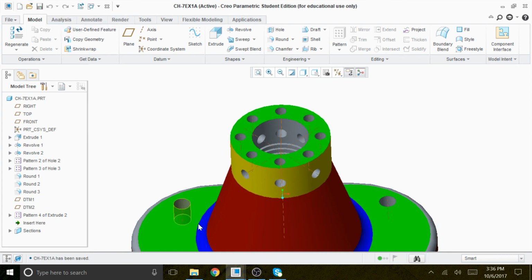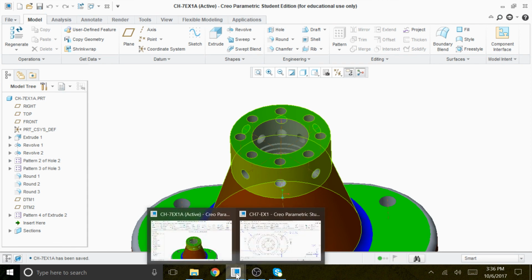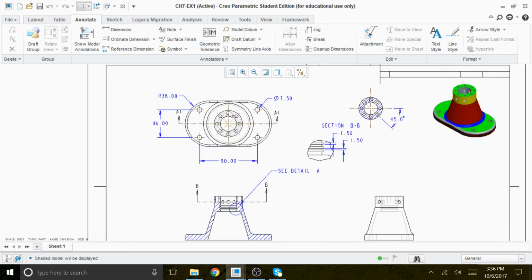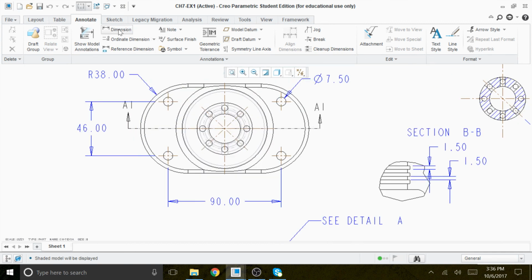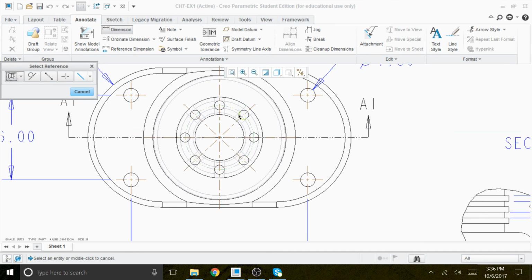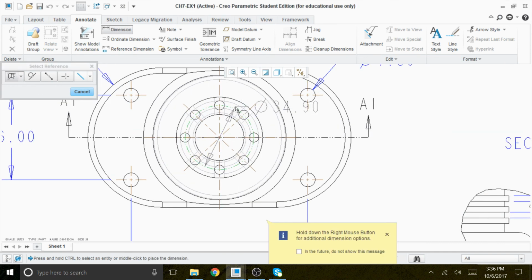Save this, and do not worry. Now we look at what happened. If I go back to my drawing, this has already been fixed, I believe, because the solid model and the drawing have a fixed relationship. Let me hold the shift and middle mouse button, go back here, go to dimension, and click on that reference center, double click, and oops, still 34.9.